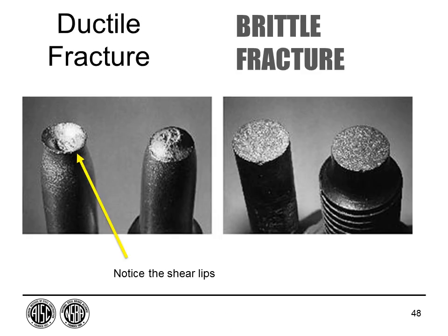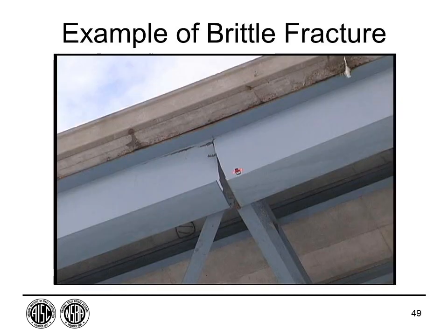If we look at ductile versus brittle fracture, of course we don't want brittle fracture, that's the sudden failure. We would much more prefer ductile fracture, and you've probably seen slides or pictures like this before, the classic cup-cone shear ductile failure versus the brittle fracture that almost looks like it's saw cut. And that's the difference. If we have to pick one kind of fracture, ductile certainly is the one we would want.